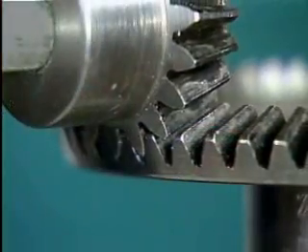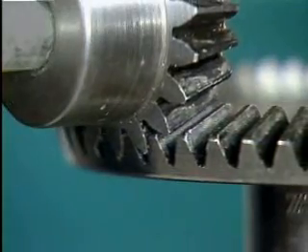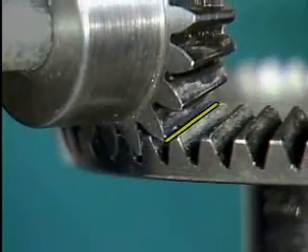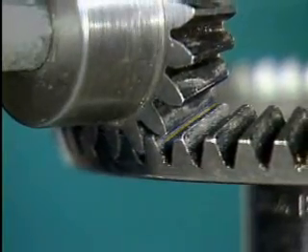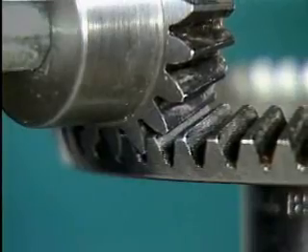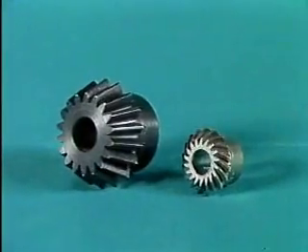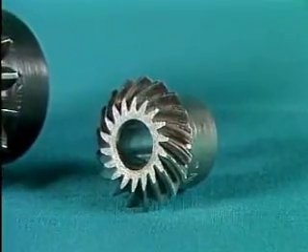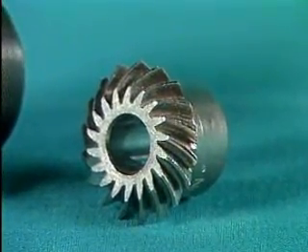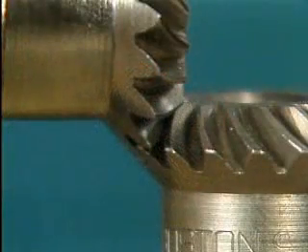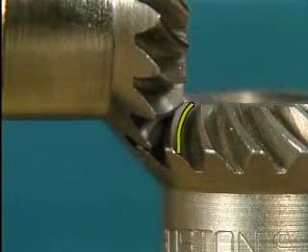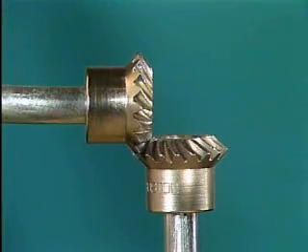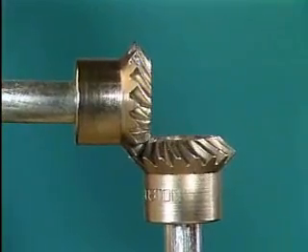Now, if you were to closely observe a spur or bevel gear set, you would see that the gears mesh across the entire gear width at the same time. When gears mesh in this way, they may produce a lot of noise. In order to reduce this noise problem, and to enable the gears to carry greater loads, some spur and bevel gears are made with their teeth twisted. This design increases the surface area of the teeth and allows the teeth to engage more gradually. Since the teeth engage gradually, the noise produced by the gear set is reduced.